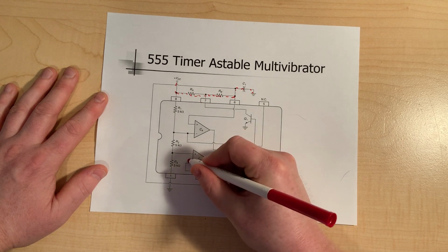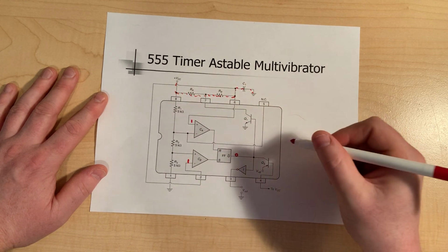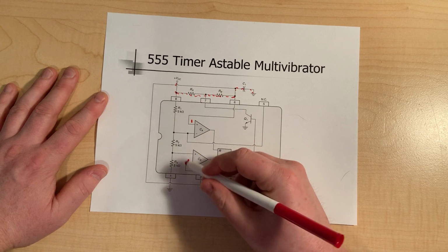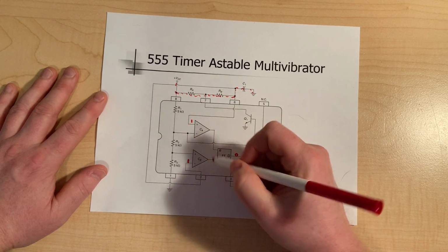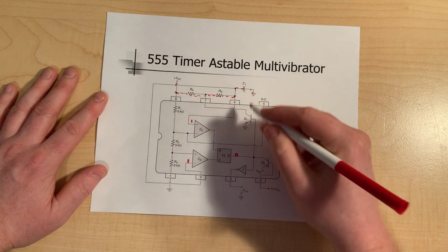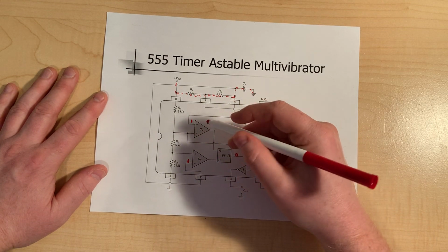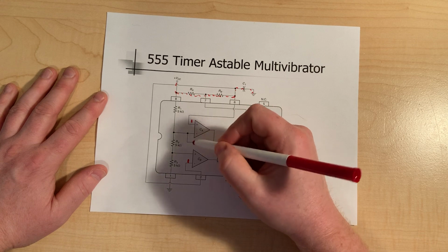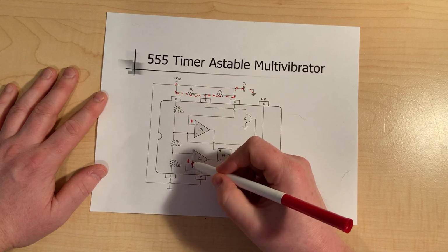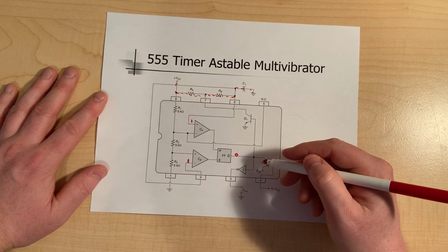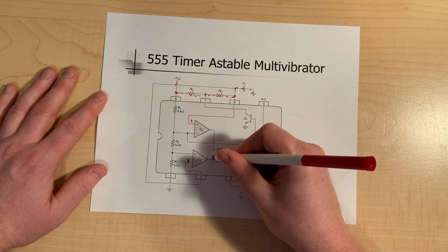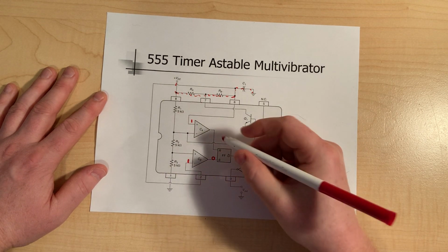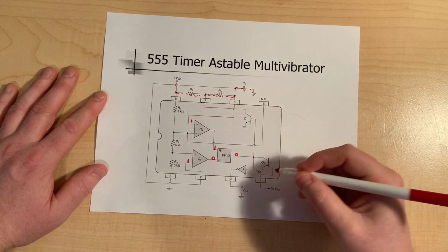Okay, so we're going to put a 1 here and a 1 here. Now, again, it's voltage potential we're talking. We're going to assume that these potentials set the flip-flop as such. As in like this, if it's a 1 here, it's going to be greater than the reference. And if there's a 1 here, it's going to be greater than the reference. So with these conditions, this sets this output low, right, because that's the inverted, and it sets this output high.